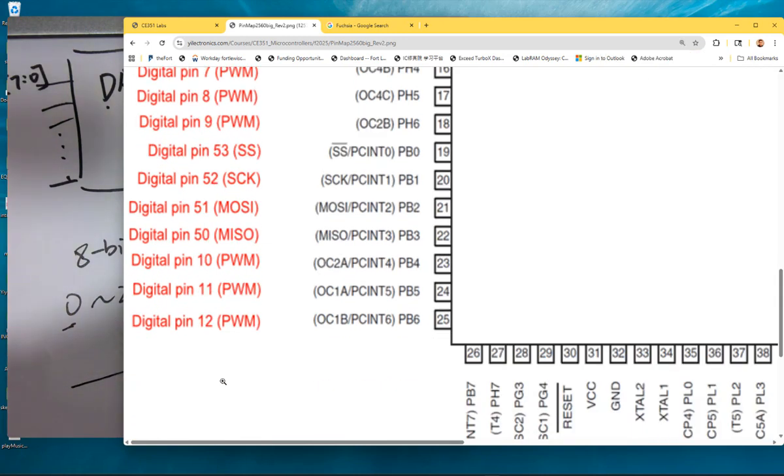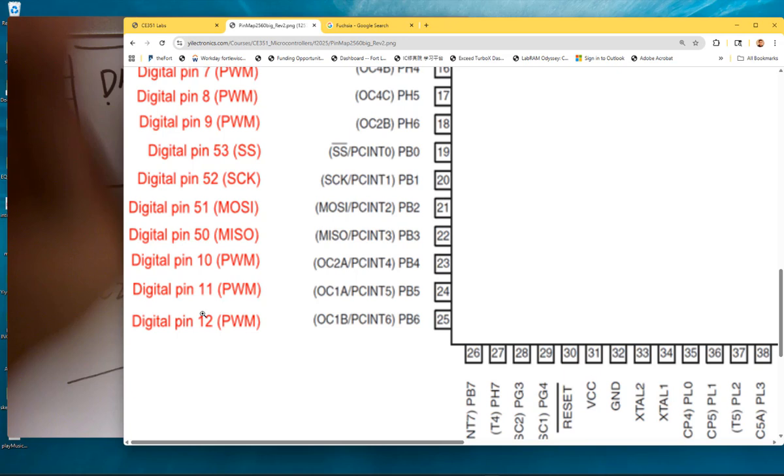Pin 10, right? So digital pin 10. When Kai designed the board, he labeled all the pin numbers. So these are the pin numbers you want to look at. So that's pin 10. When you are trying to use that PWM output from the board to control something, you can find that pin number and connect it to your LED. So pin 10 will be used for that case.